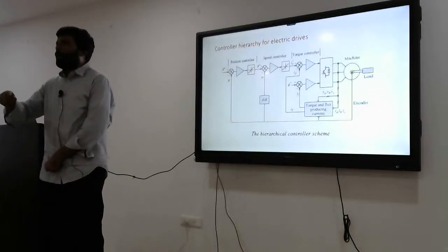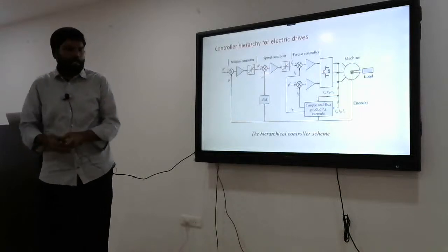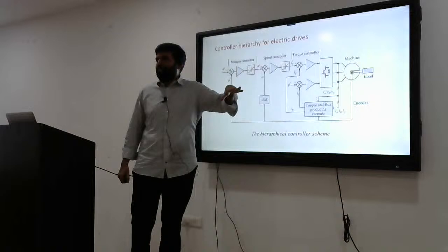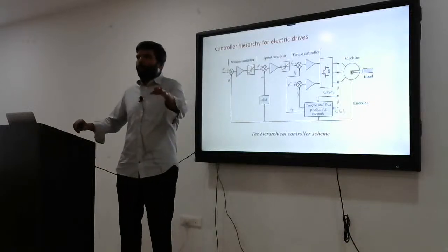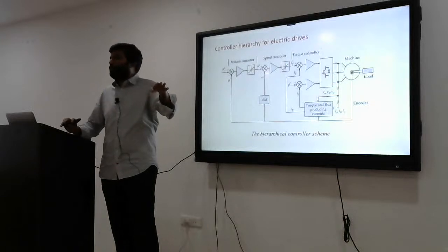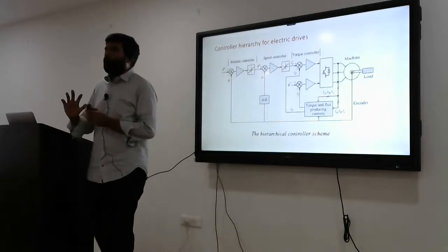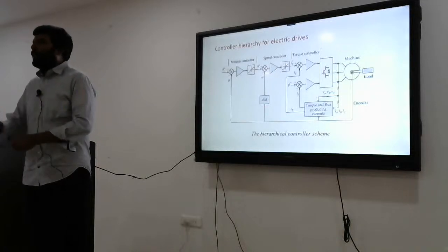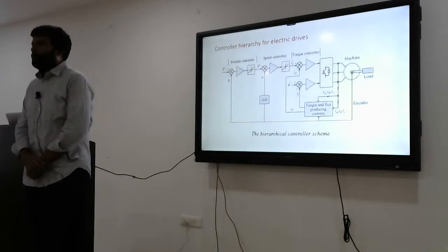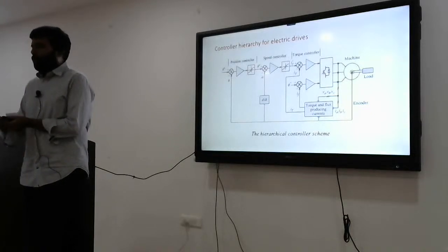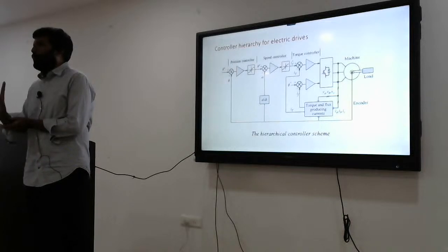To decrease the number of variables involved in the torque expression, they are taking one more path for maintaining magnetizing flux constant. The main object of this path is it will maintain air gap flux constant whenever you want to control the speed below base speed. If you want to control the speed above base speed, in the flux weakening zone, this path will take care based on the required speed. So finally, in case of electrical drive, any drive, target variables are only torque and flux.